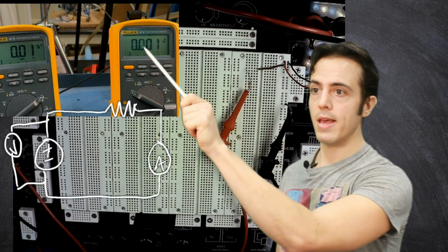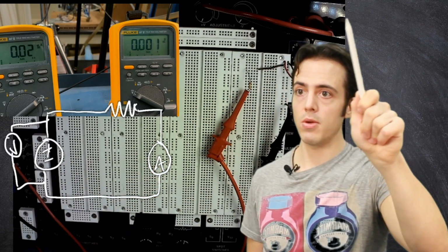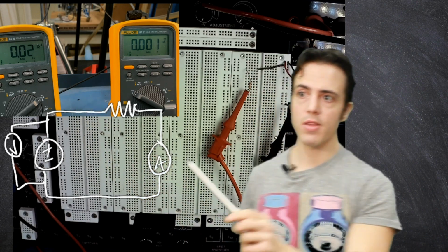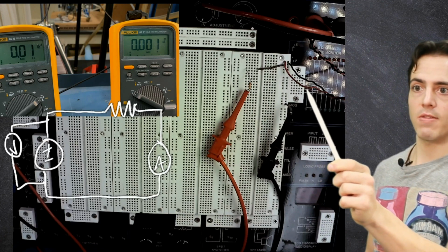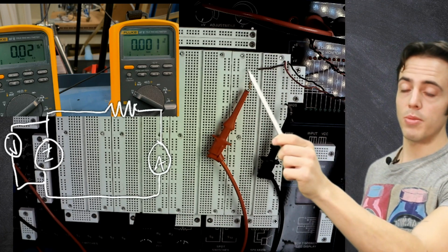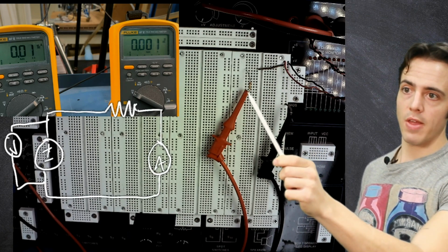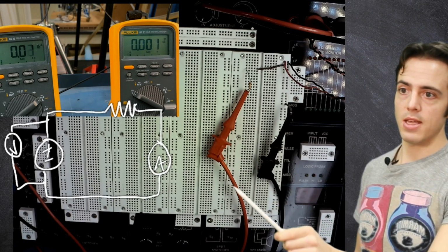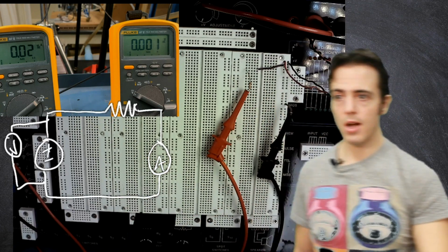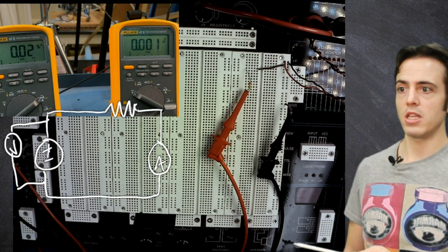So this voltmeter here is connected across, because we've got these 2 cables just connected to the power supply. The ammeter is connected in series, and that's because it's providing the positive voltage to the resistor, which is coming out the other leg, and then the circuit is being completed out of this cable, which goes into here, measures the current, and then comes back out here, which is connected to this rail, which takes it all the way to the power supply.